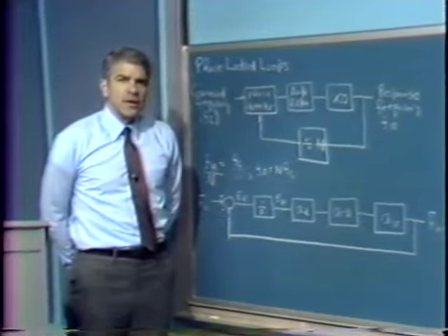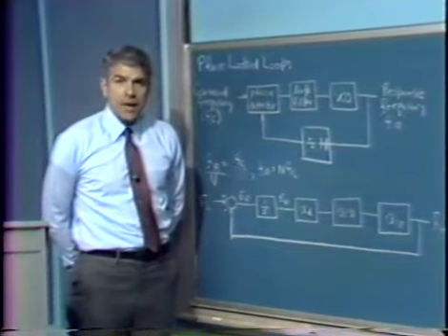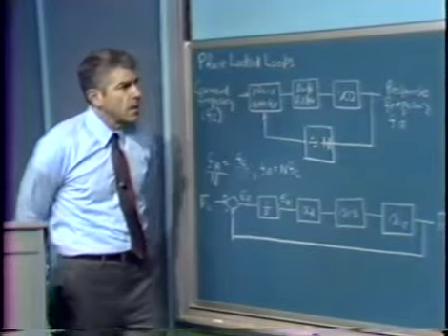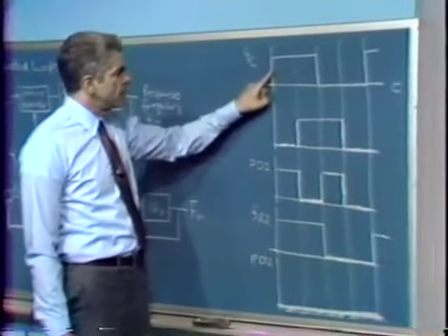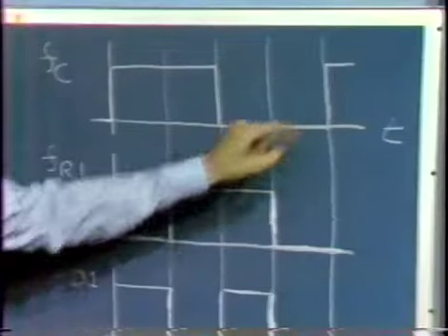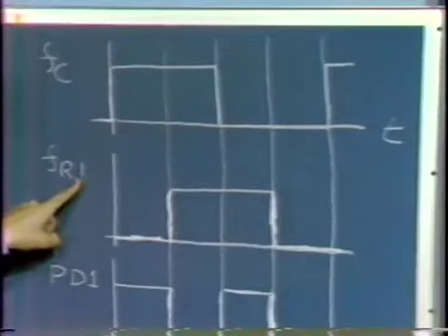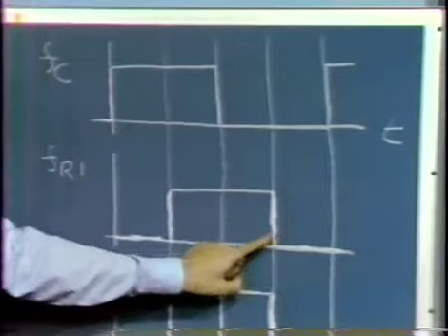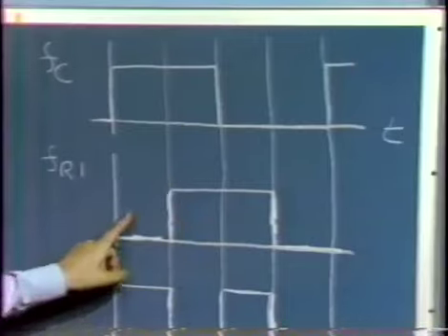One very simple way is to use an exclusive OR gate if the input signal and the output signal of our phase-locked loop are both digital signals. Let's look at how that might work. Suppose our commanded frequency is the digital signal with a phase as shown, and assume that the response of the system is again a digital signal, phase shifted by 90 degrees in time, by a quarter of a cycle.